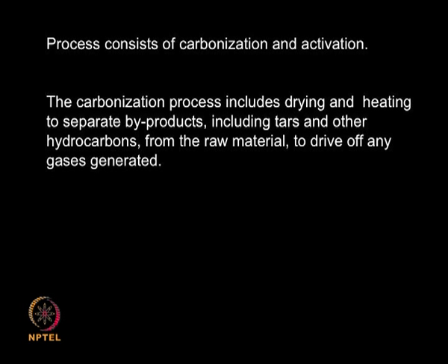So here what do you do? You have a carbonization process and then you have the activation process. So in the carbonization, you include drying and heating to separate the byproducts. The byproducts could be tar, other hydrocarbons from raw materials and other gases. So all these are to be dried and removed completely, which activates your material, which activates your carbon, and hence it becomes an activated carbon.